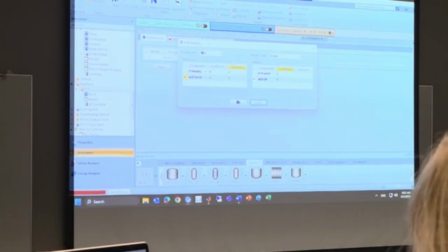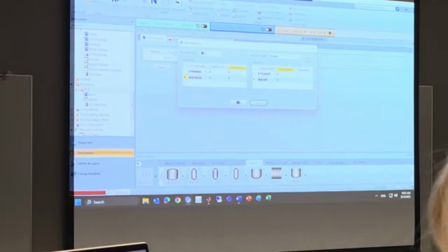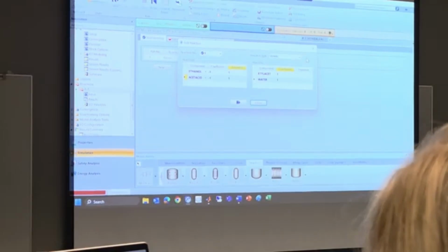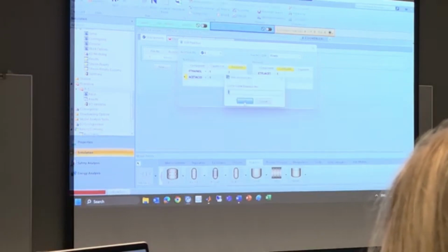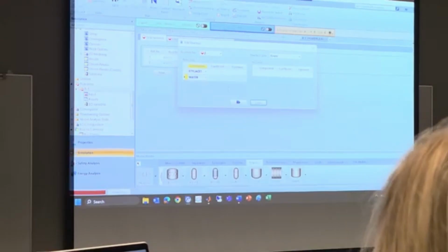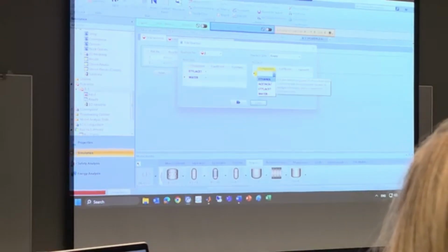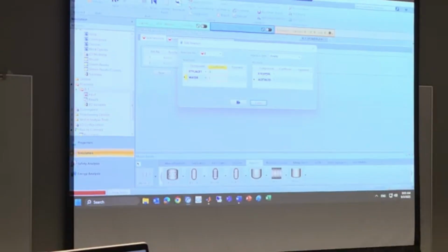If you look at your reaction type, it's called kinetic or equilibrium. We will look at it in more detail later. Today we have kinetic information, so we use kinetic reactions. And we have another reaction, the reverse reaction. So I will enter ethyl acetate and water here, producing ethanol and acetic acid, with the stoichiometric coefficients and a first order reaction.